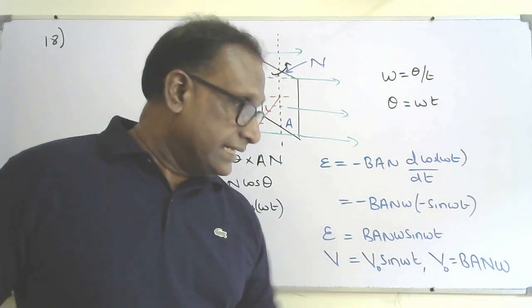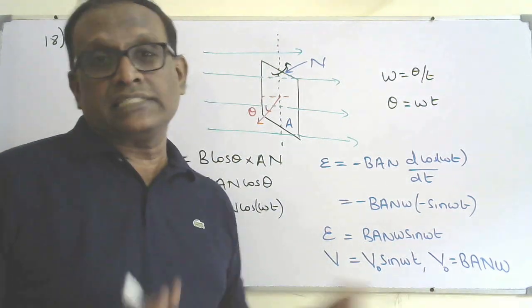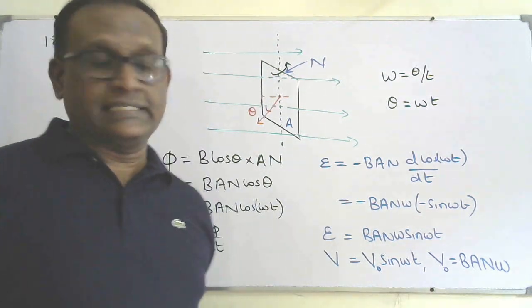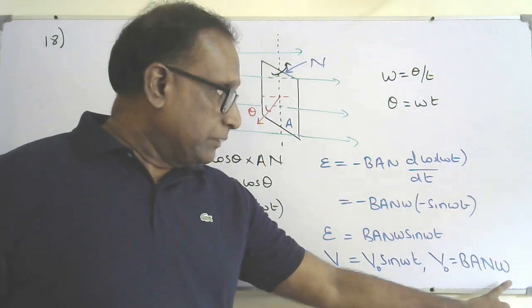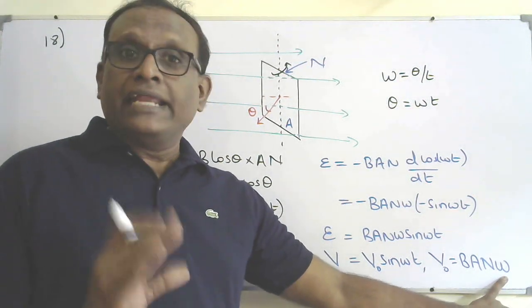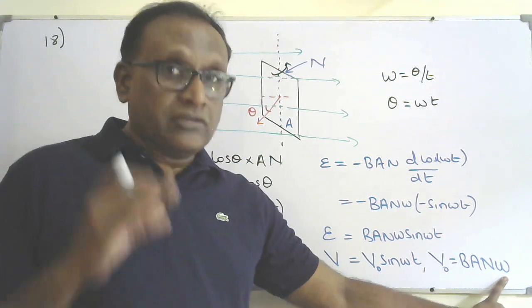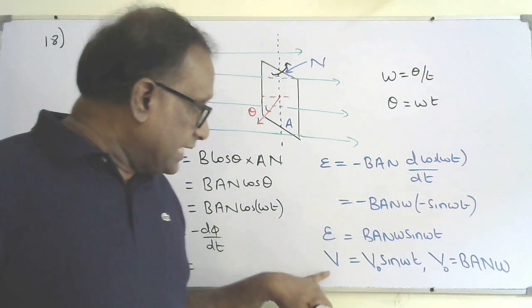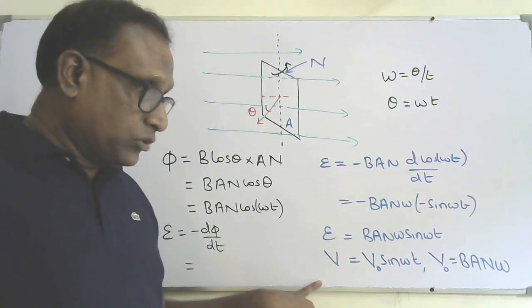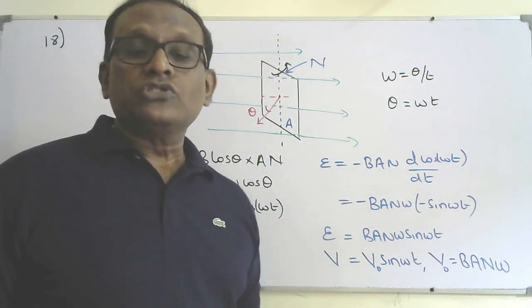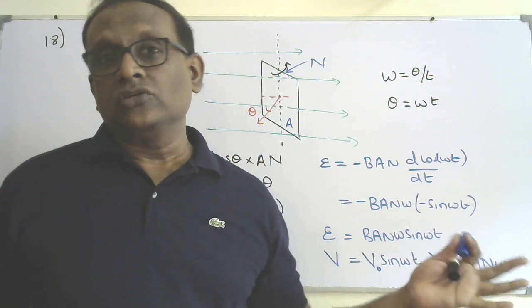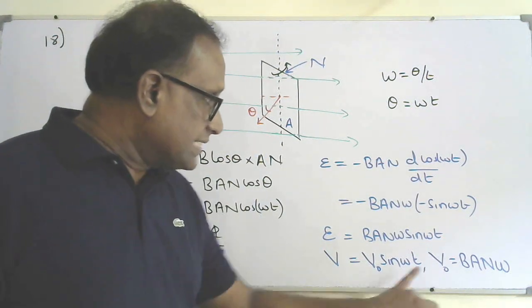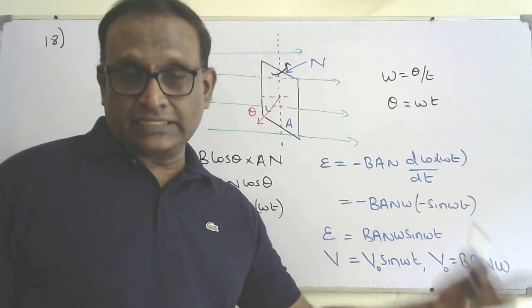That's a question asked in this part, but we don't use these equations in A level, but this is the actual explanation. So you can see the peak voltage depends on angular speed. If you maintain the angular speed constant, frequency of rotation constant, you will have constant peak. So this is a sine shape. That's the reason you can see on page 21, the induced voltage is varying according to a sine curve. The V against time graph is a sine curve.